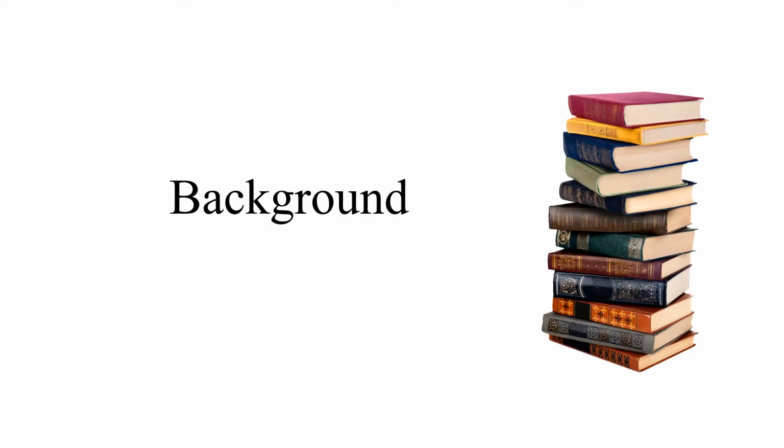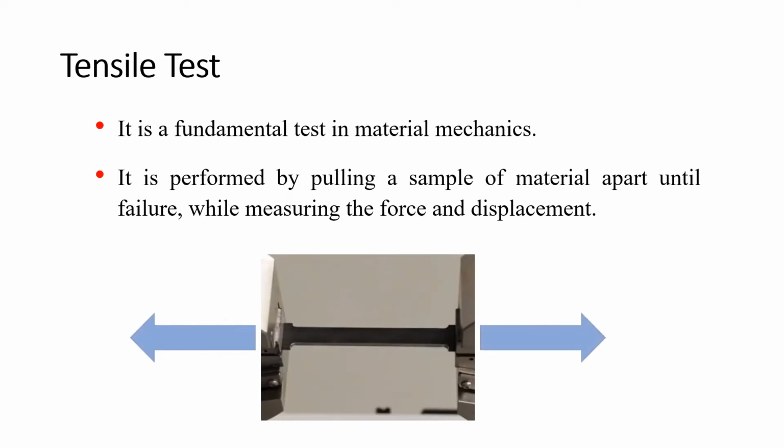Background. Let's start with the tensile test. Tensile test is fundamental to understand the behavior in material mechanics. It is performed by pulling a sample of material apart until failure, while measuring the force and the displacement.